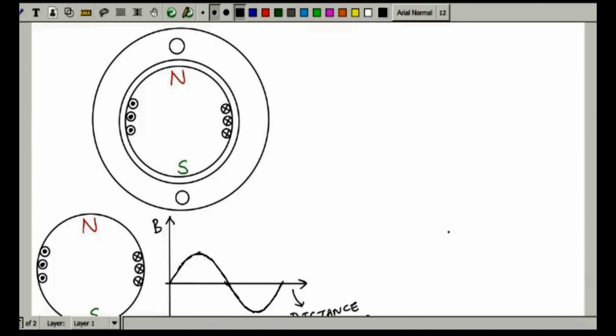First of all, you can see here that this coil, let's say this is your coil side A and this is your coil side A dash. So you can see that coil AA dash is a full pitch coil. Now, in which manner have we concluded that coil AA dash is a full pitch coil? The answer is very simple.